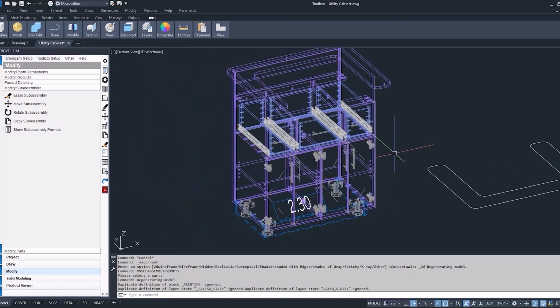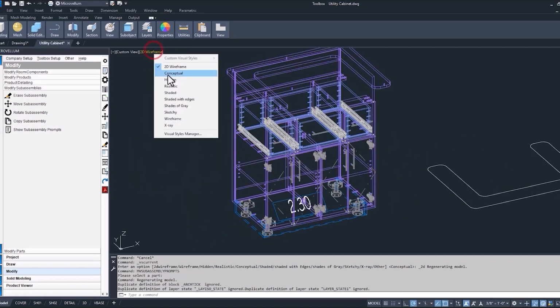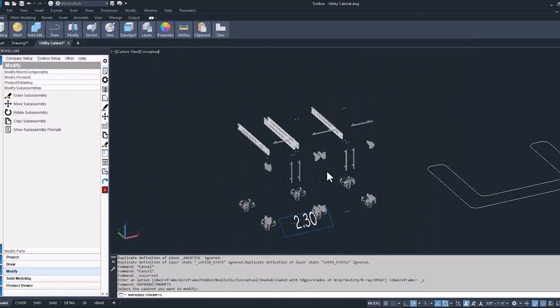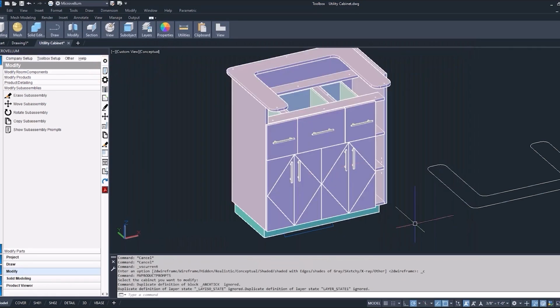Now before we end this video, I do want to show you what happens if we make a change to the width of this cabinet. So now that we've updated the width of the cabinet, the corners that we picked originally aren't updating with that new size. So I'm just going to go through this pretty quickly and show you what we need to do to get this cabinet working the way that we want it to if it were to now be 4 inches wider than we had set up originally.